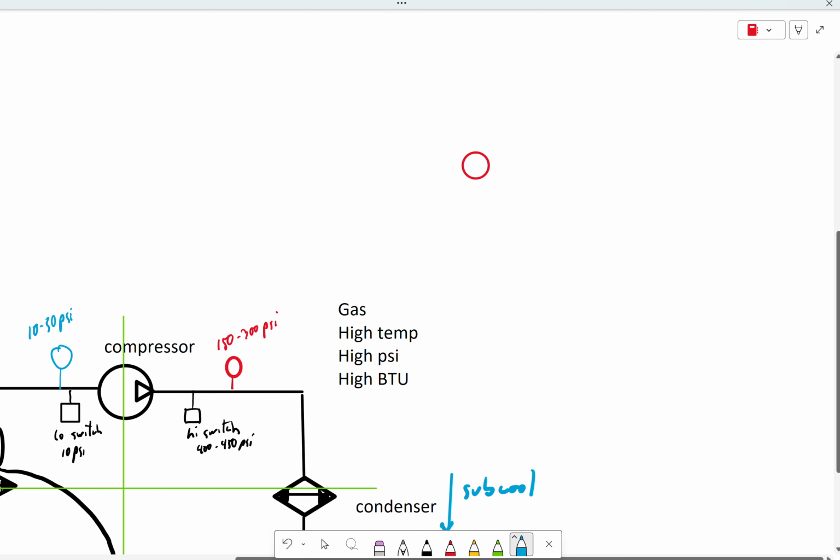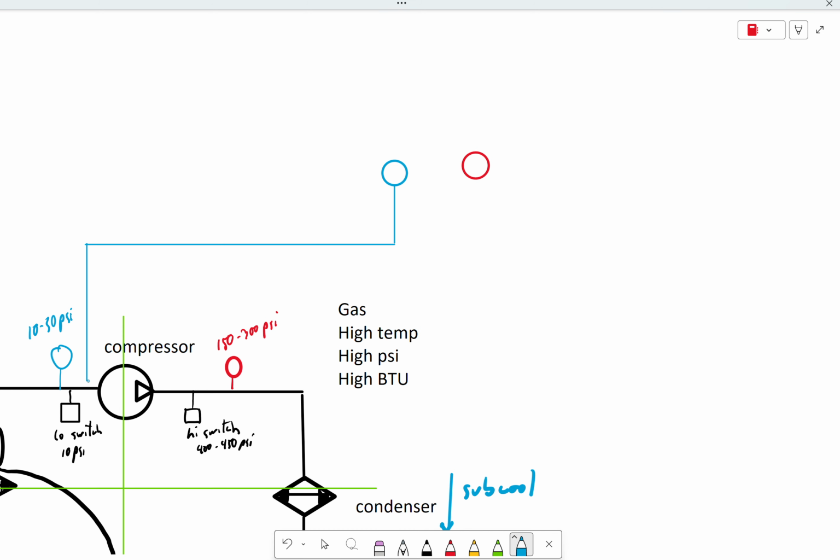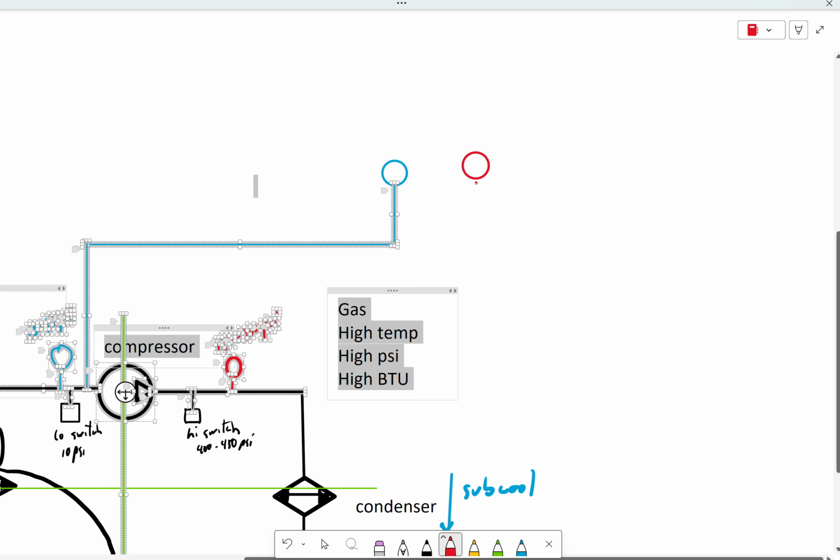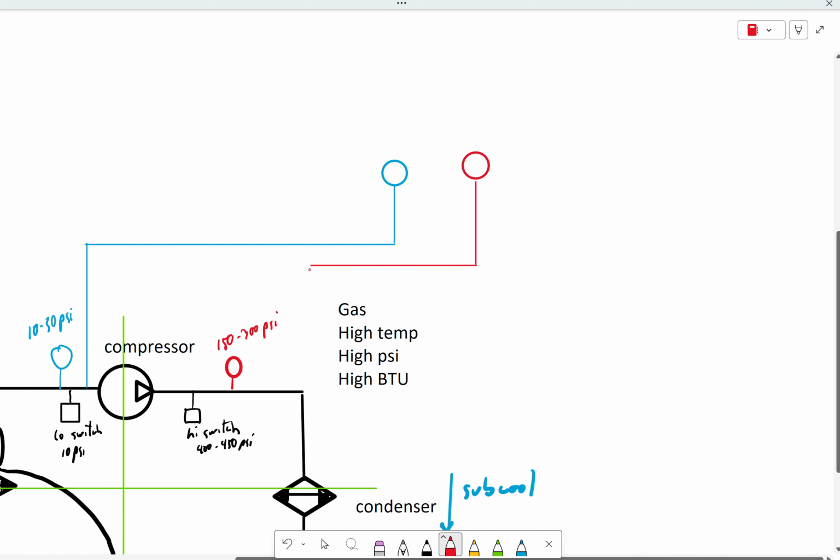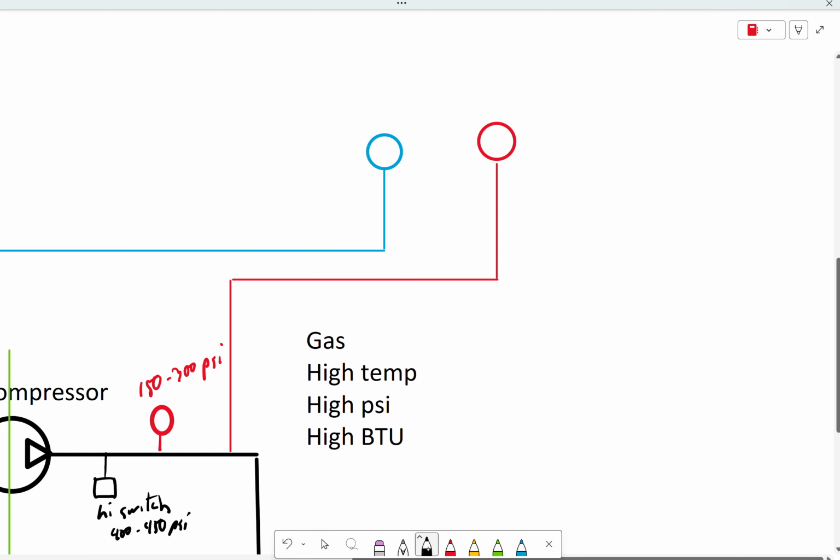Okay? So this one's going to have 2 gauges. Your low side is going to connect over here to the low side service coupling on the system. The high side connects to the high side service coupling on the system. Okay. And then you're going to have a manifold in the middle of this. That manifold is going to have a couple of hoses coming off of it.